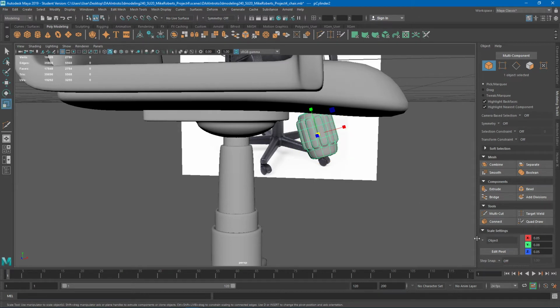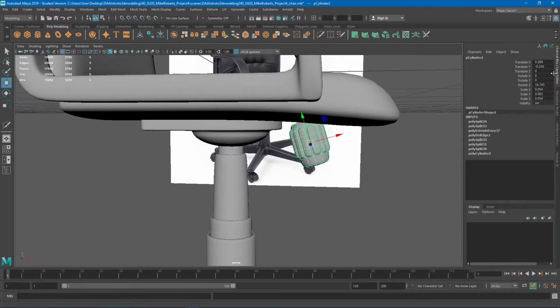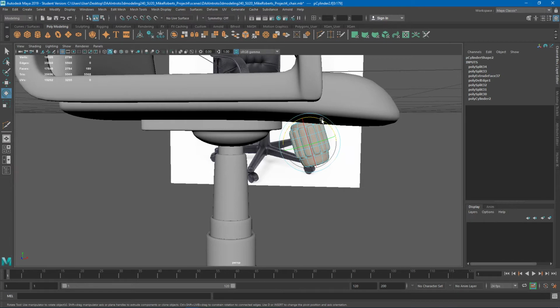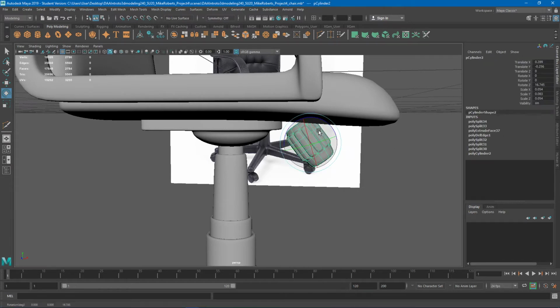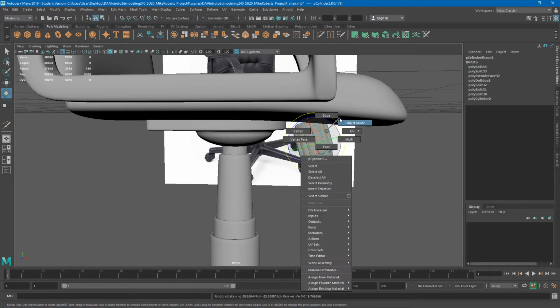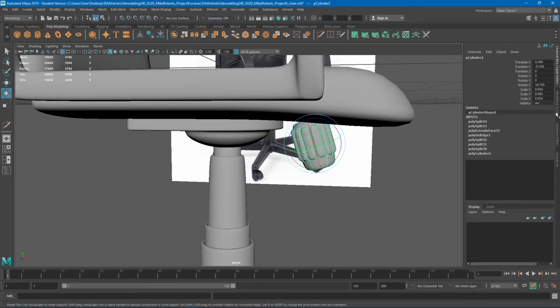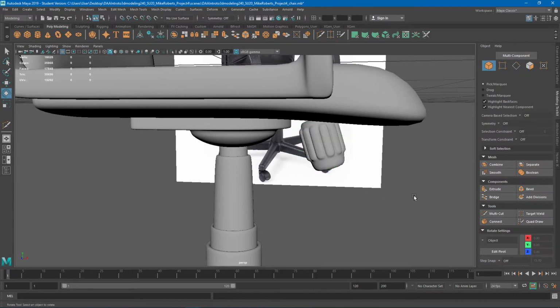So you'll see, kind of neat. If you ever want to manipulate it based on an object, that's what object does. You have to have changed these values at the object level though. If I was to do this at the face level, if I was to go in here and select those faces and rotate them, you'll notice that even in object mode, the actual object doesn't line up to it anymore because I rotated all the faces. So keep in mind that has to be an object level transformation. You have to have actually rotated and moved it at the object level, in object mode, and then that's when your object level will work. Kind of cool.